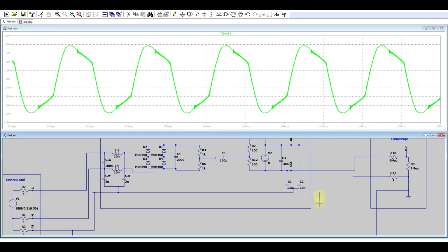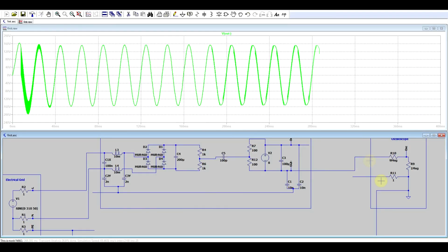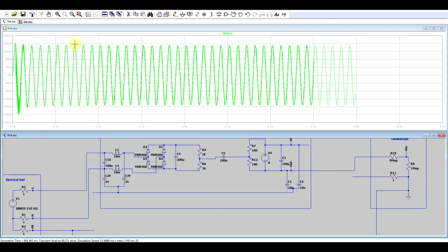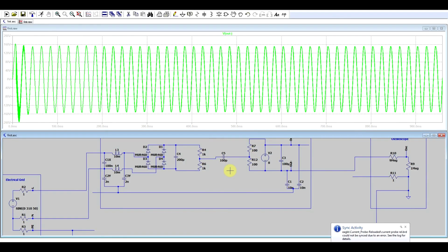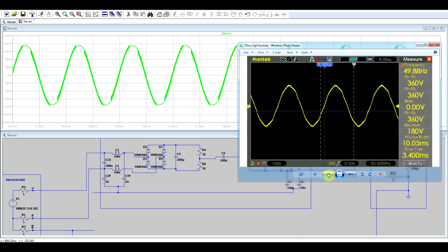Now the next thing we can look at is what happens when we disconnect the protected earth. We've seen that this helps, but it's not recommended. And if we simulate, we can see one of the reasons why. Using the same setup, I'm no longer getting 1 volt or 2 volts or 5 volts of ripple, I'm getting 300 volts of ripple. Basically, the mains power supply is directly coupled through this stray capacitance into the oscilloscope. In the simulation I'm getting roughly 310 volts, and in reality it's around 360 volts.